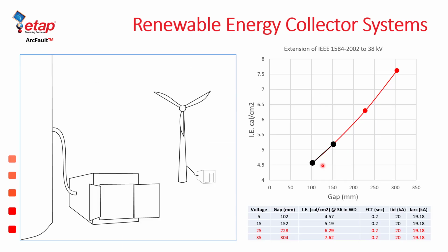Because of this, for enclosures around wind turbines of different sizes, we have developed a model that can extend the IEEE 1584-2002 equations into this domain. We have also added capability for the ArcFault module to handle this type of equipment.